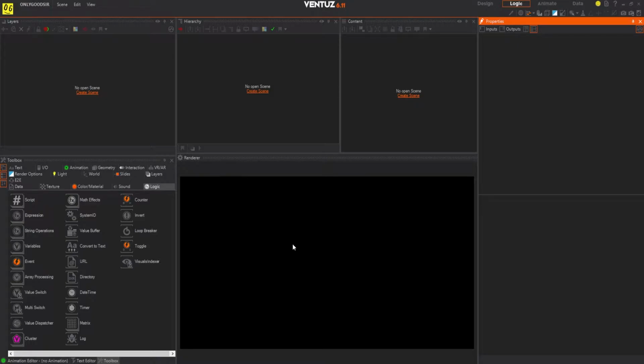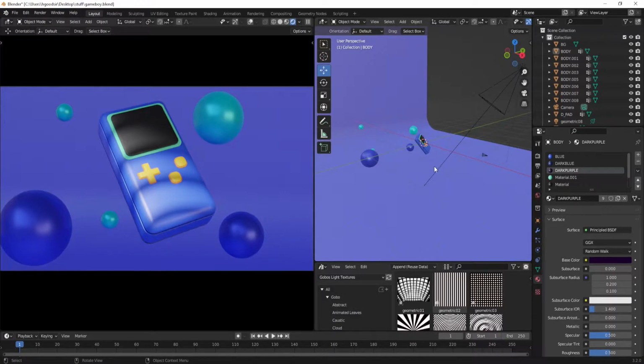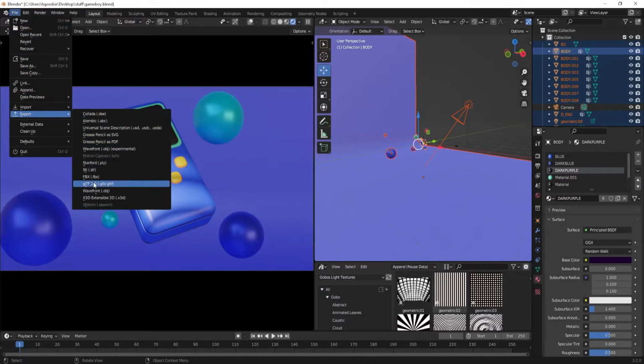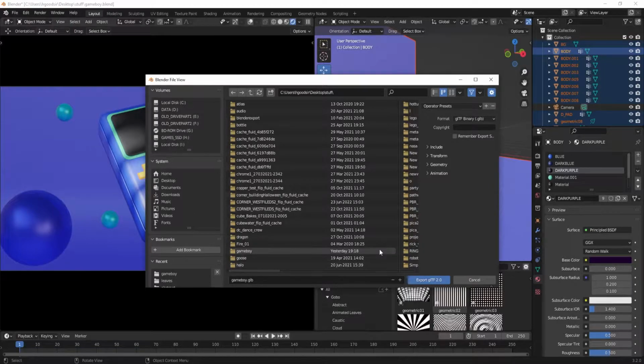So with Blender, the first thing, in the properties when you're exporting your objects, like I said before in the first video, if you didn't watch the first video, is that when you're exporting, you export as a GLTF file. Sorry, there you go, I got it right. Under geometry, make sure you apply your modifiers, because if you don't, stuff like bevels or solidifies or whatever you use won't apply. So make sure you apply the modifiers and then they'll apply.